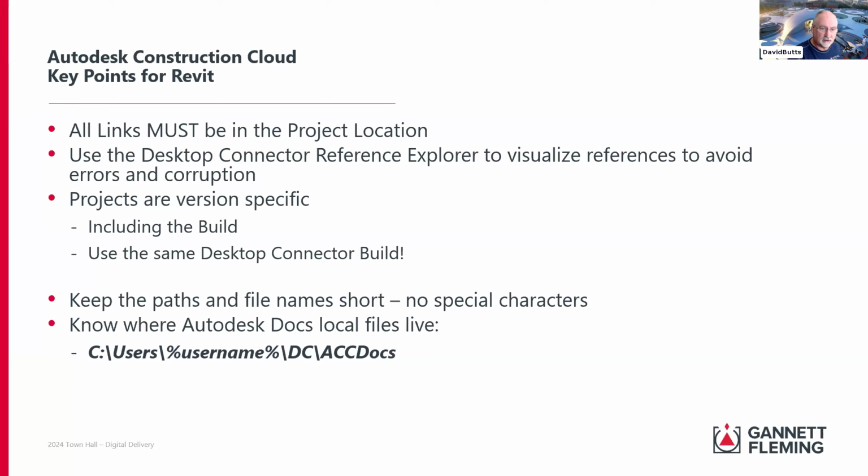So those are some of the things that we want to make sure that everybody's on the same release. You have to be on the same build. You cannot have one user on 16.3, one user on 16.5, one user on 16.6. You do not want to do that. So make sure that when you set your projects up and you communicate as a team, this is a critical item for users. And again, most of the problems I see on the forums that pop up, this is a frequent case of where somebody has an old build and they're just having problems syncing and things are not working correctly.